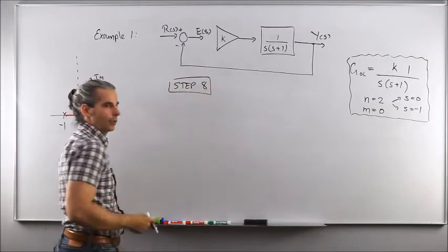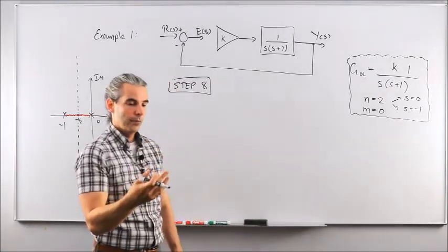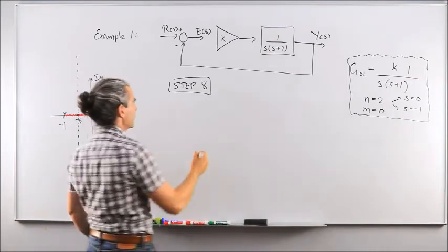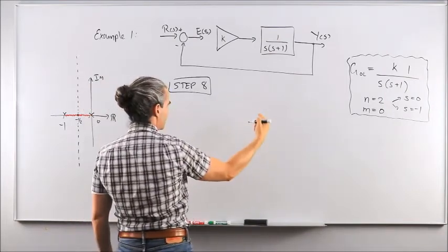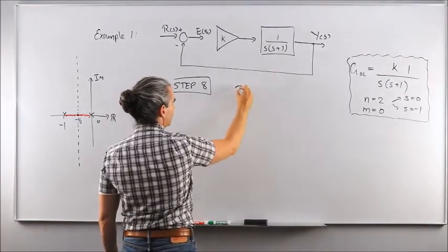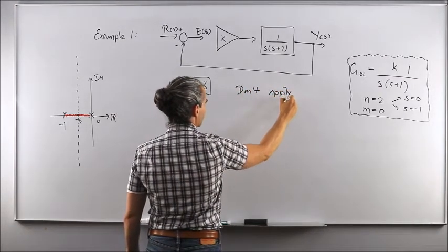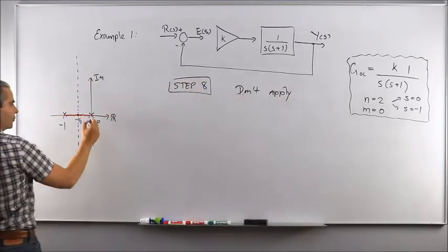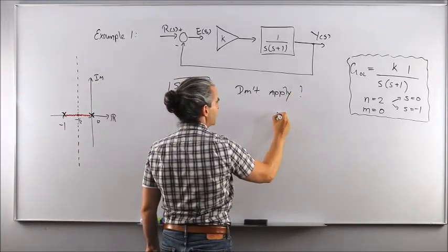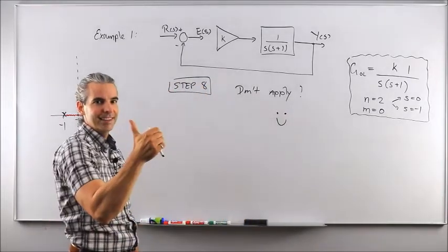That's where we were talking about arrival and departure angles from poles and to zeros, okay? But here, from complex conjugate poles all the way to complex conjugate zeros, but here we don't have any complex poles or zeros in our situation, right? All we have for the open loop transfer function are two real poles. So that equation doesn't apply. And that makes you super happy because you've just saved 5-10 minutes doing an exam. Yes.